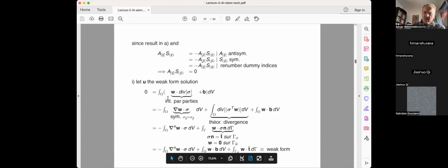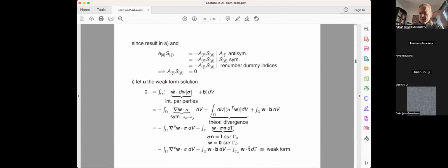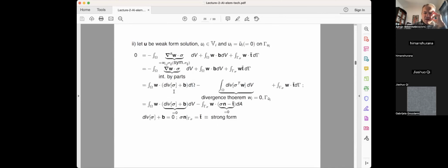So the conclusion from this development is that when you start with a strong form, you can always go and obtain the weak form without any difficulty. Just follow the steps and you get there. On the other side, if you start with the weak form, that is your starting point, to get the strong form, you can do that if you get more than what you argued for, because when you start, you don't really need regularity of the stress field in order to compute derivatives.